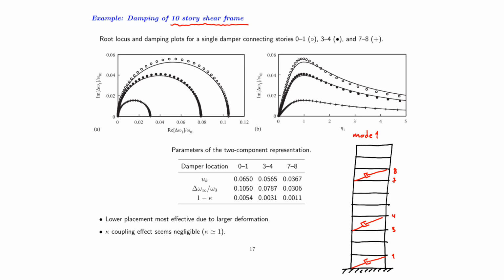You should remember that the mode shape for a shear frame structure has its largest curvature at the bottom, and then it becomes almost vertical for the upper stories, a little bit exaggerated in this drawing. And that means the stretching is much larger for the bottom floor than for floor number between 7 and 8. And that is immediately seen in the displacement vector, indicated by the amplitude. And remember that UK is equal to the connectivity vector for our configuration times the undamped vibration shape, and U0 is indicated here by green in the right bottom figure.